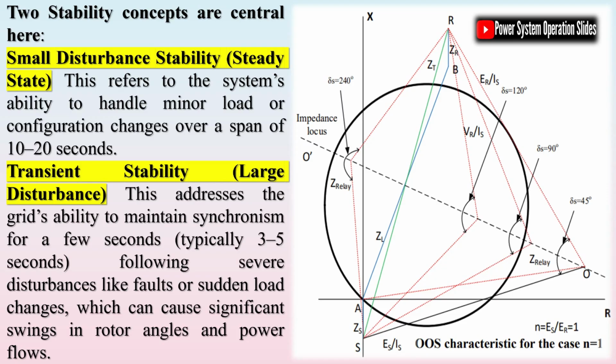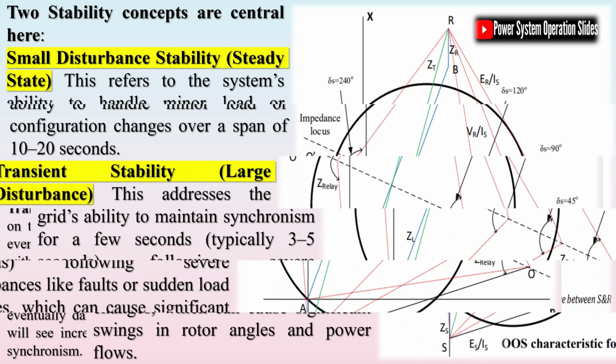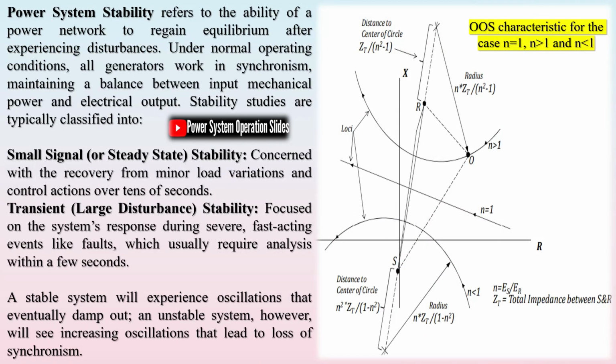To ensure effective system control, these protective schemes are typically applied at critical network locations, often near the electrical center, with additional measures such as transfer tripping schemes used to manage separation in specific scenarios. Notably, OS tripping is designed to avoid triggering when the phase angle nears 180, as this could impose harmful stresses on circuit breakers. This approach effectively minimizes cascading outages, limits load loss, and preserves service continuity while protecting equipment during both transient and unstable conditions.